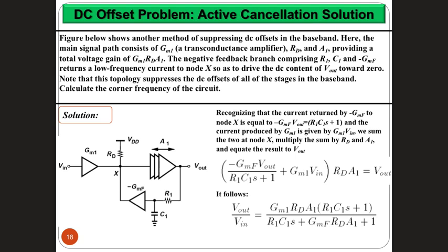The idea is to low pass filter the output to get something very close to the DC component, and then multiply it by a specific negative gain so that it becomes equal to the actual DC value before going through this stage, because you are sampling after the last stage. When you add this negative to the input, you end up with DC removed, but in an active fashion. The previous one was passive.